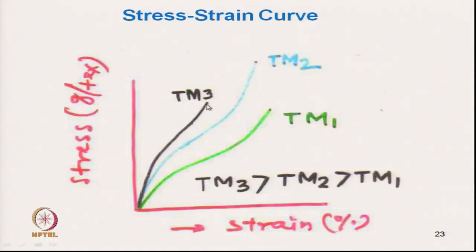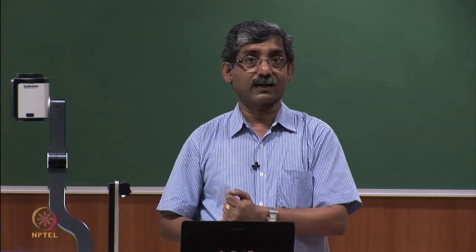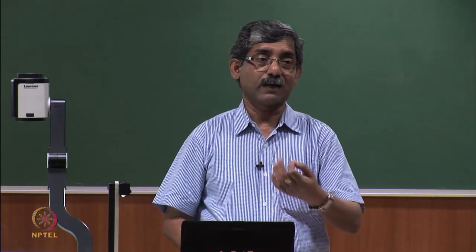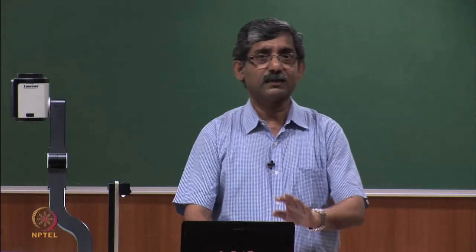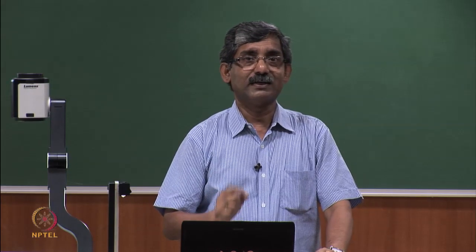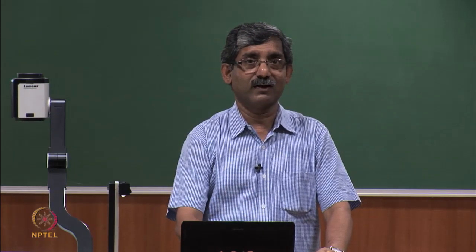Due to the obliquity effect of the fibers, the actual final breaking stress drops, although the initial modulus is higher. Looking at the stress strain behavior, one can predict what is happening there. These are the different factors which affect the stress strain behavior of textile material.